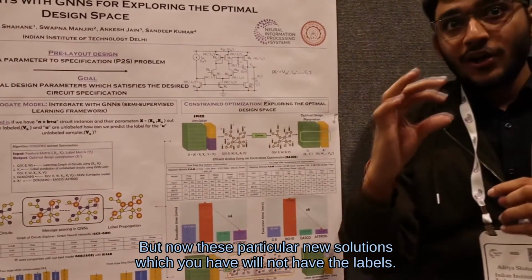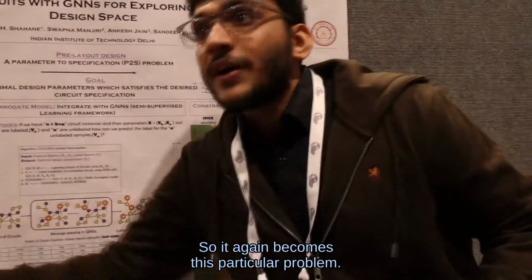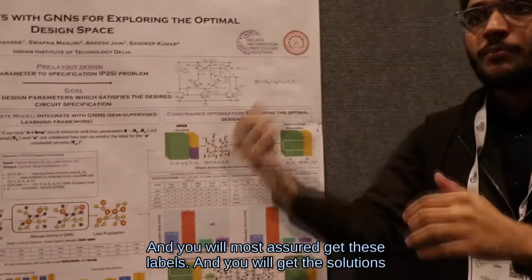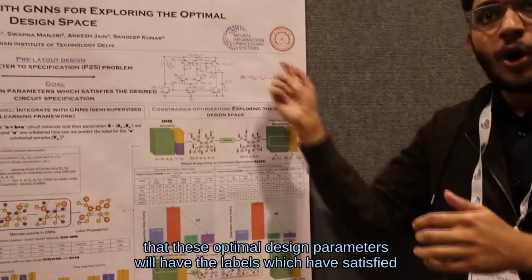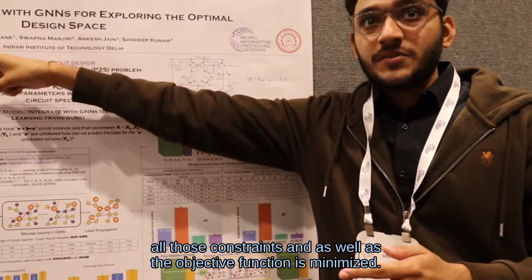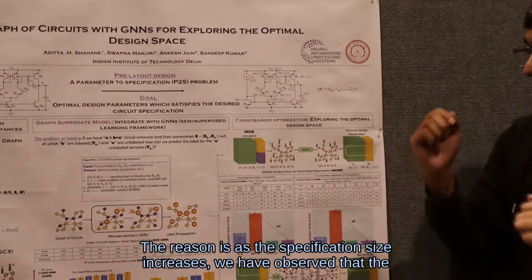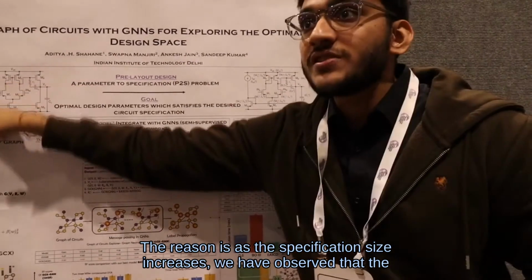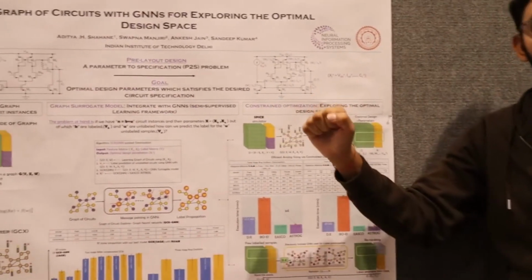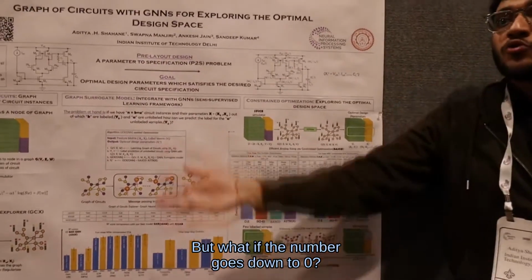But now these particular new solutions which you have will not have the labels. So it again becomes this particular problem. So what you do, you learn a graph and do the label prediction, and you will be assured that these optimal design parameters will have the labels which satisfy all those constraints, and as well the objective function is minimized. But what is the problem? Why do we not stop at this particular place? The reason is, as the specification size increases, we have observed that the chances of getting those particular nodes might end up at 0, right? So initially I mentioned that there might be 20 nodes, but what if the number goes down to 0, right?